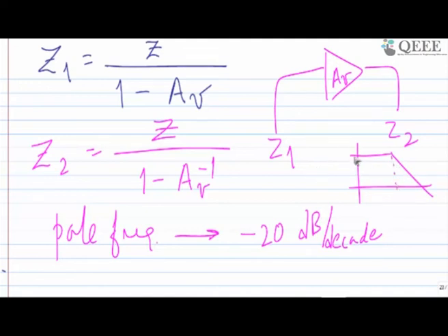Means for a simple RC circuit, your gain is 1 till the frequency called 1 by RC, and after that there is a roll off with 20 dB per decade, and it's getting cut with the x-axis.